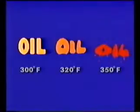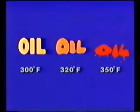Now that we know some of the causes of overheating and some of the signs of damage, how do you check for the problem before it causes damage? The answer is easy. Oil thins out at 310 to 320 degrees Fahrenheit, causing ring and cylinder wall wear. It breaks down completely at 350 degrees.